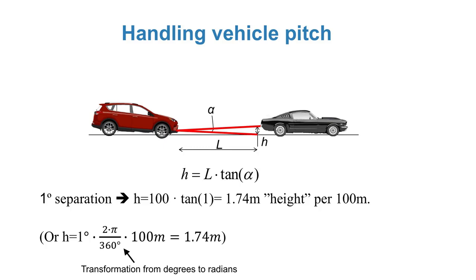Note that the same calculations can be used for angular resolutions horizontally, for both static and rotating LiDARs. A LiDAR with a 1 degree angular resolution horizontally could thus miss hitting a car, at least for one individual sweep at the distances of 100 meters. This since many passenger cars are less than 1.74 meters wide.